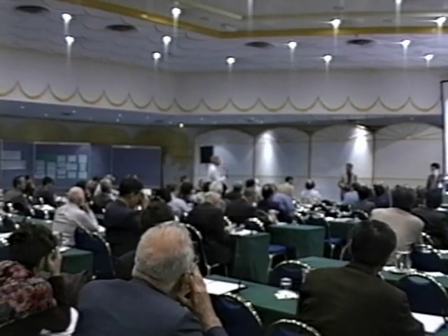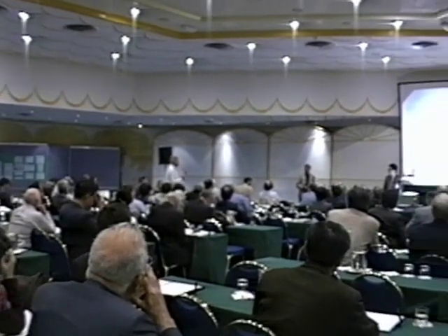I'd like to compliment you on a very nice presentation of some careful industry. And I suggest that you actually have 3 effective methods to obtain higher loading. Two of them you put up there: chemical etching with aqua regia, and vacuum heat treatment. The most important variable is an adequate and reproducible method of producing the metal. The etching is useful, the vacuum treatment is useful, but you've got to have good metal to start with, and it seems that the contribution that you have made is a procedure that can produce a palladium stock which is suitable for loading experiments. Thank you.